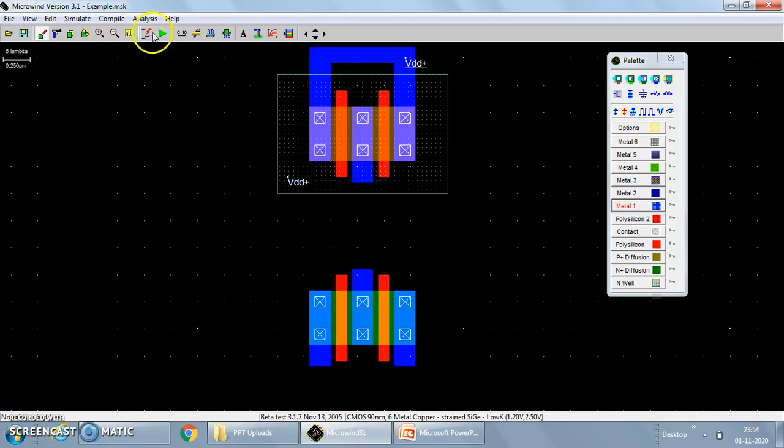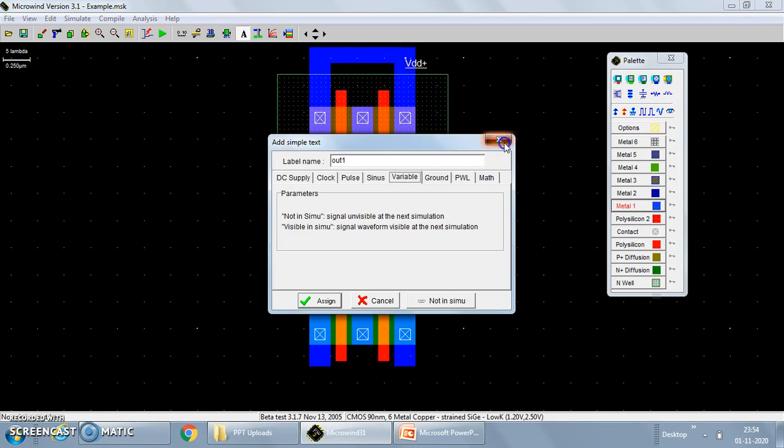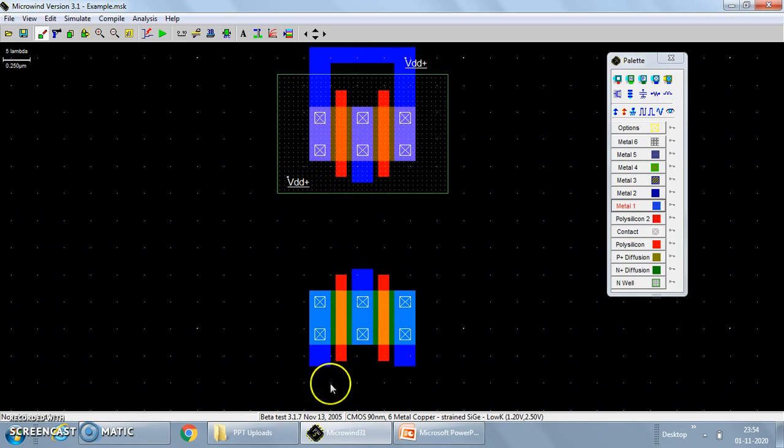Then what next? We can give the proper labels also here. So I will call, or we can give it that at the end. We close this. Now next is, what about both the source of N MOSFETs are grounded together. So we'll extend this layer again. Same metal, I will choose the same layer. Extend this layer for both the sources. And then I will join these two layers. Okay. So here what is to be connected? Source of both the NMOS are connected to the ground connection. Fine. Now what next? So I will call this as a source, gate, drain. Again drain, gate and source.